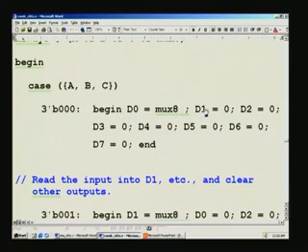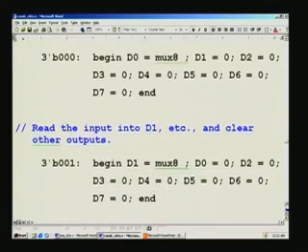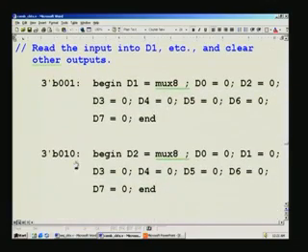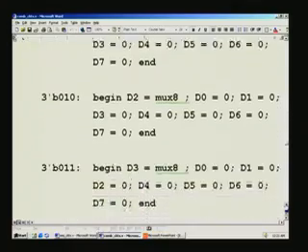So, what happens to the other outputs? You have to force them to 0. If you do not, you may land up in a problem later on, because it might have come from an earlier state with 1, so it latches on to that condition if you do not mention it. This also we have seen while dealing with RTL coding guidelines. And similarly for other cases, all the 8 cases are considered here, and in each case you see that mux 8 is assigned to the corresponding output. This 4 corresponds to this 4, although it need not necessarily be so.